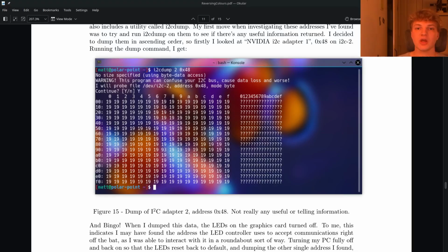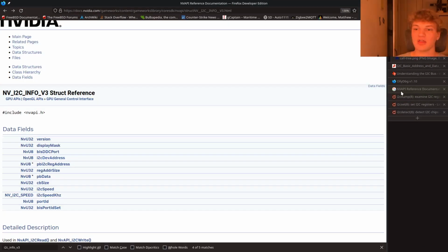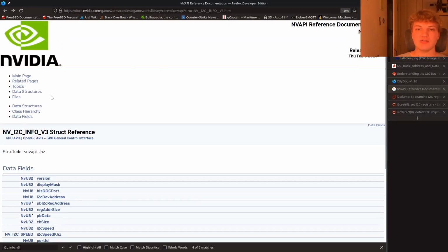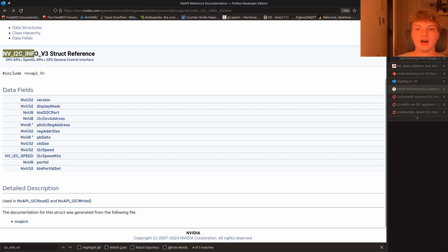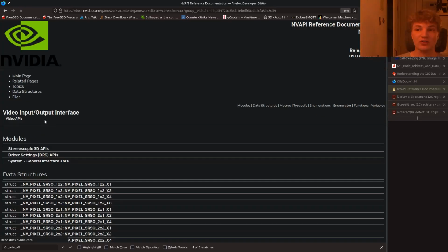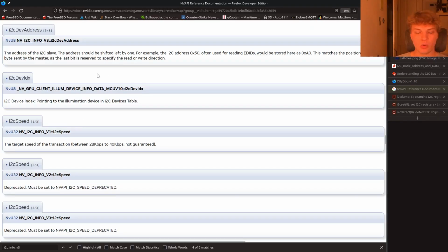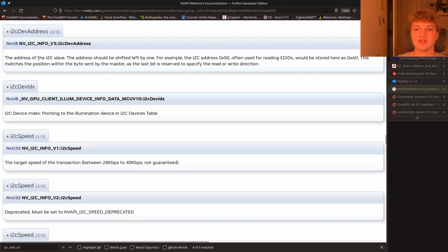Now, if you remember earlier, I said keep in mind we get calls to nvapi.dll, and while I was researching NVAPI, I came across this right here. This is on the NVAPI reference. It's a struct called NV_I2C_INFO_V3, and there's a field in this called i2c_dev_address. If we go to the definition for that, you'll notice this is the address of the I2C slave. The slave address gets shifted left by 1.